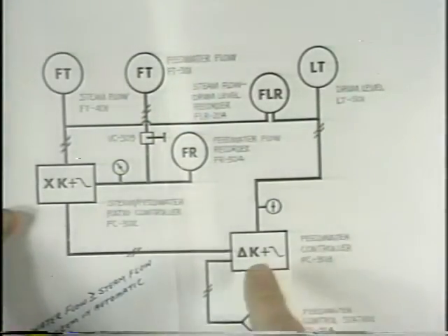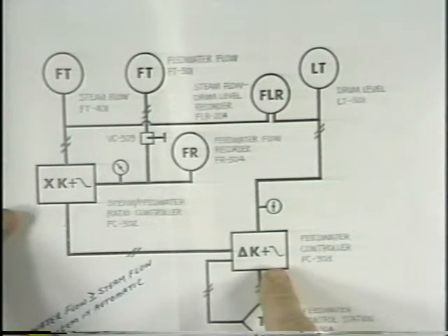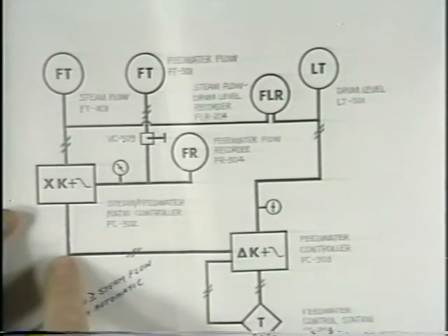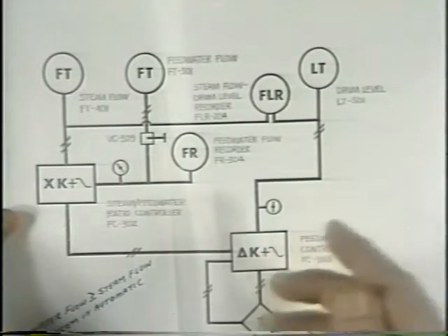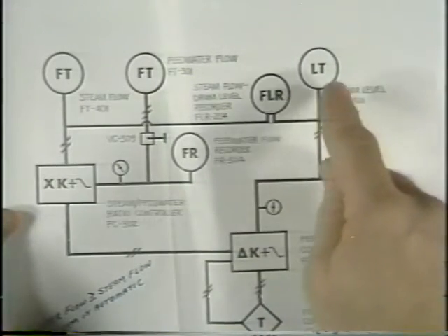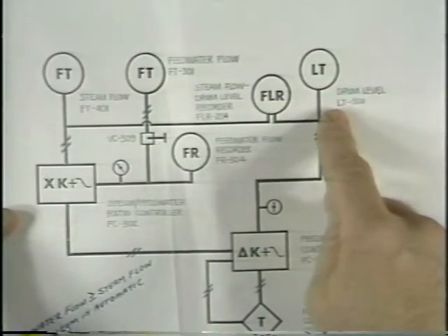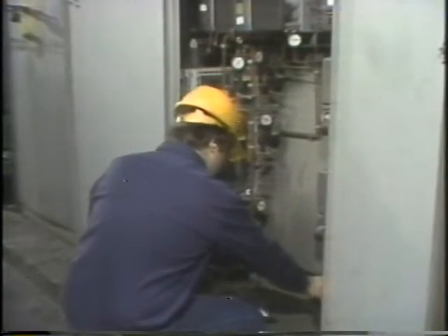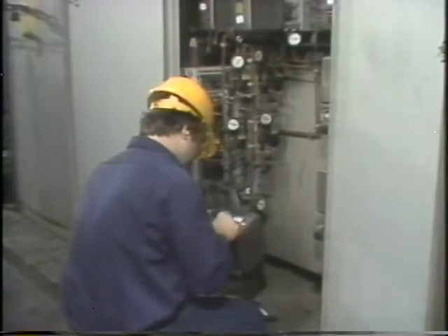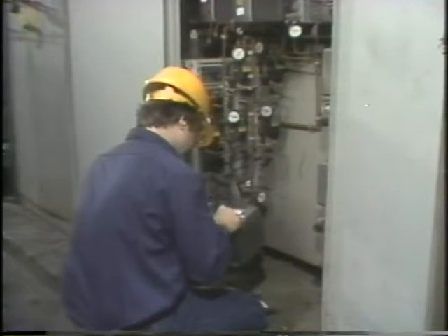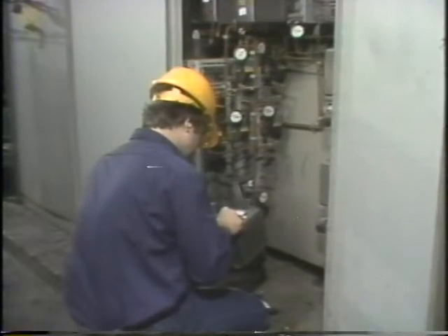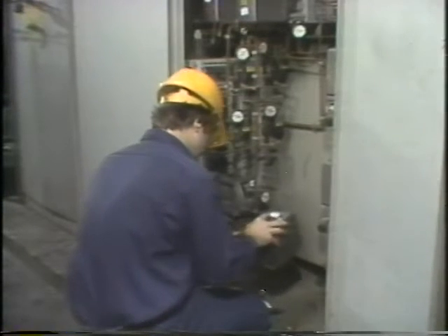You know, if the feed water controller is out of adjustment a bit, it could be receiving the correct signal from the ratio controller, but just be enough out of adjustment so that it won't bring the drum level back down to where it should be. I can check the calibration sticker to see when it was calibrated last. Oh yeah, it's been a while since this controller was calibrated. The controller's output could be high due to some calibration changes with time.